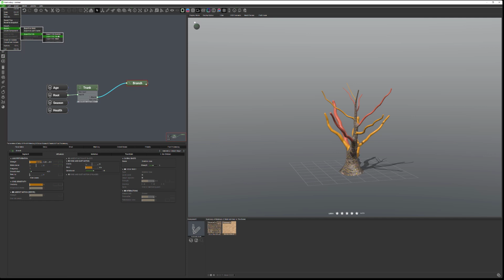With extend, if you use a bridge, if you have a special link between, use a bridge between Cinema 4D, then your view environment will be inside the Cinema 4D, and those properties will work in that case. But if you export just straight out objects, those properties won't be available. It will be like a locked model, which still works nicely in many cases. And you can obviously use it in Unity, Unreal, and other game engines if you need that as well.